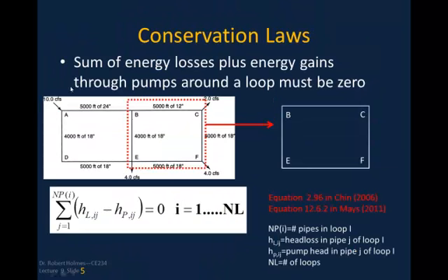So in this situation, I've got 10 CFS coming in here, and a reasonable assumption might be to assume 5 CFS going this way, 5 CFS going that way, because I know that I've got 10 coming in, I have to have 10 going out. Then I've got 5 coming in here, so I will have to have 5 going this way, and as I come into this node here, I've got 5 going here. I'm paying attention now, and I know that I've got to have 4 going out down here, 2 going out here, 4 going out here. So I'm going to have to play with this and make assumptions in BC, BE, EF, and CF that would make sure continuity is preserved at every node in my first estimate.